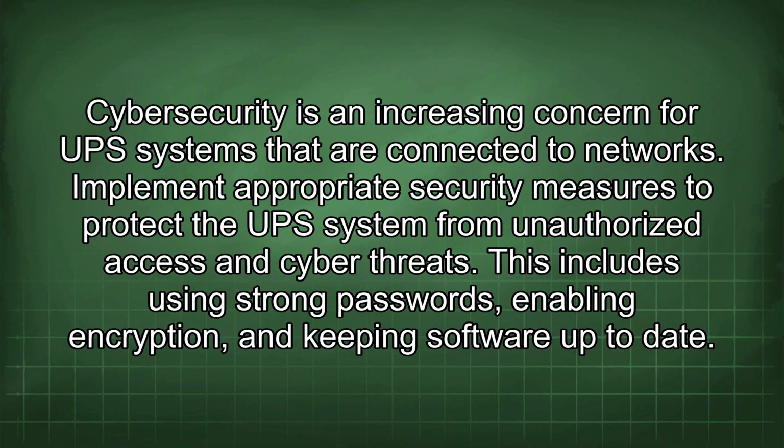Cybersecurity is an increasing concern for UPS systems that are connected to networks. Implement appropriate security measures to protect the UPS system from unauthorized access and cyber threats. This includes using strong passwords, enabling encryption, and keeping software up to date.